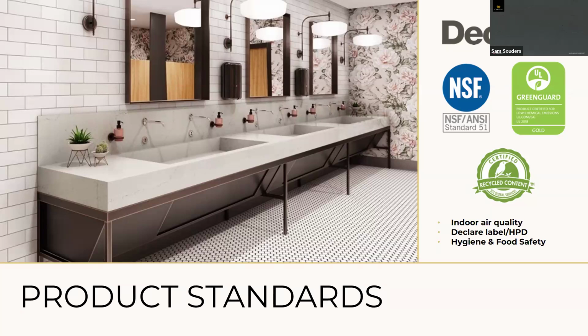Food contact certifications. Quartz surfacing, unlike natural stones, is extremely dense and non-porous. These characteristics help prevent the absorption of food materials, which makes it easy to clean. The combination of non-absorbent and easy to clean resists staining and reduces the potential for bacterial growth due to food and liquid absorption into the surface. As such, some quartz surfacing is NSF/ANSI 51 certified for food preparation and splash zone areas. NSF is for 3 zones: food or direct contact, splash, and non-food or service areas.